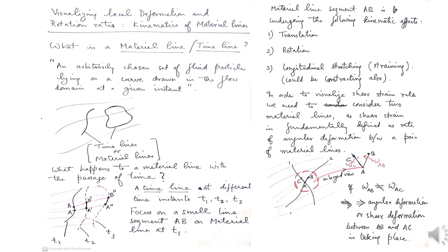So now, with the passage of time, it is expected that while fluid particles A, B, C all will translate, there's a very good chance that the angle between AC and AB would also change. Now, in the enlarged view, I have shown the necessary condition for the angle between AB and AC to change. It's very easy to say that if the instantaneous rotation rates of AB, shown as omega AB,